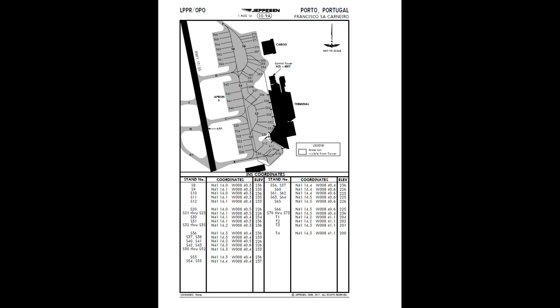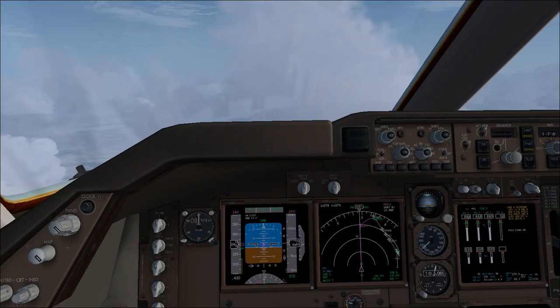We will now calculate the landing weight, set the VREF and approach speeds, and set the auto brake selector, which we will keep on auto brake 2 because we calculated it's fine for the runway. So back to the cockpit.